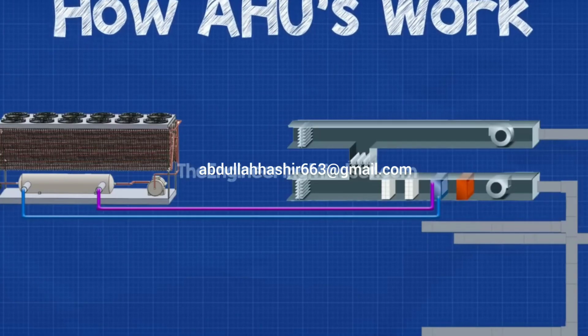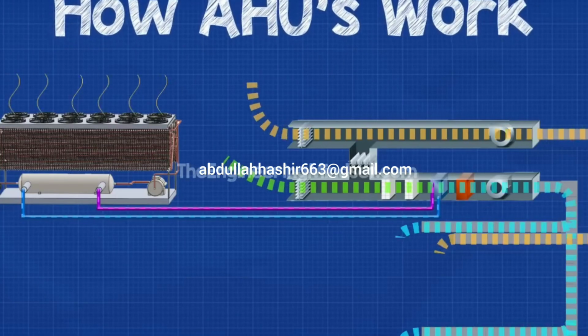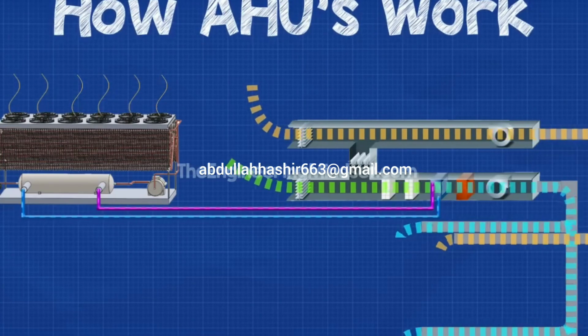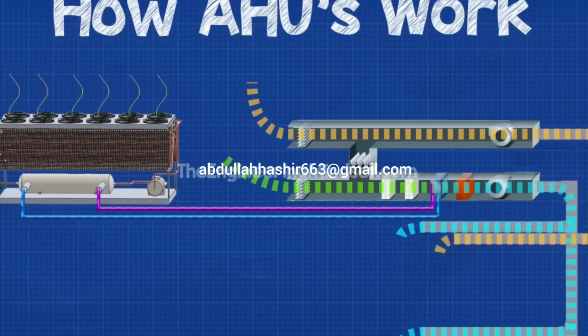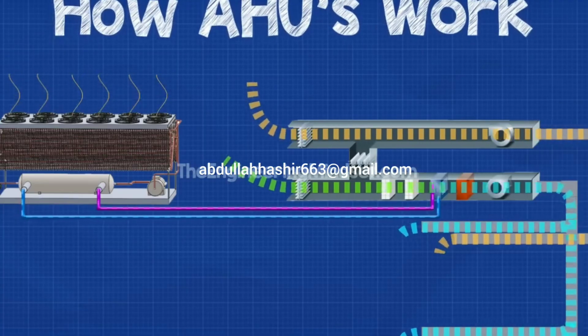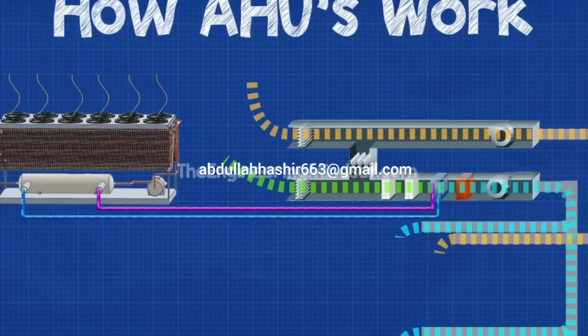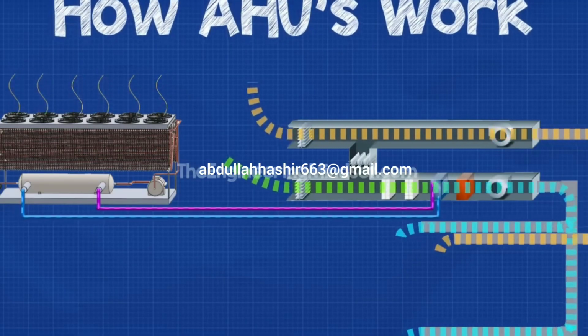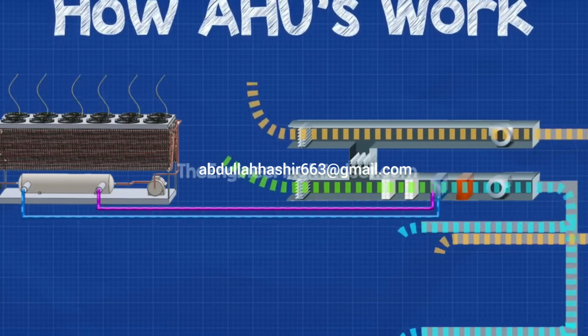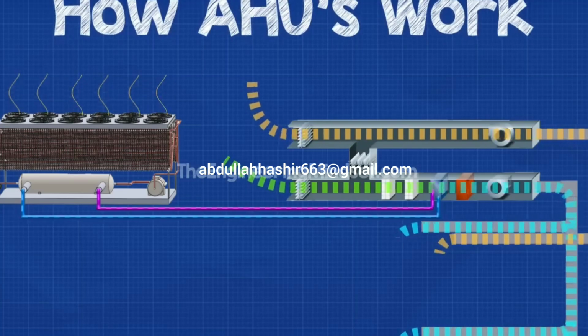In a simple form, an AHU will use a fan to suck in fresh ambient outside air, which will then pass through some filters to remove any dust and dirt. It will then pass through the cooling and heating coil heat exchangers, which, as discussed, are typically fed from central plant units. Once the air has passed over these coils, it will be pushed out around the building.